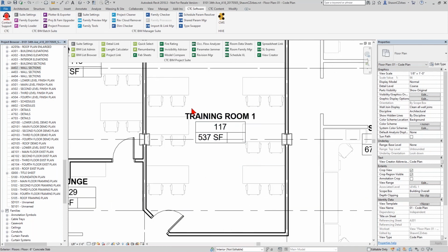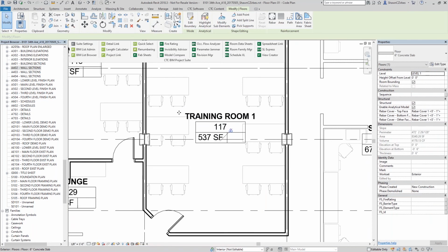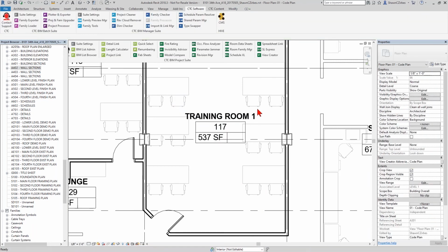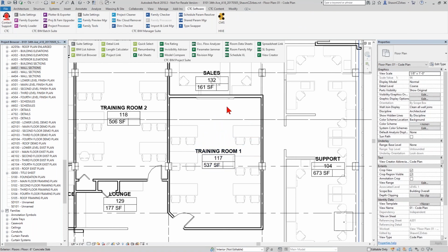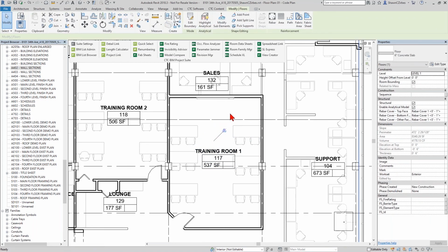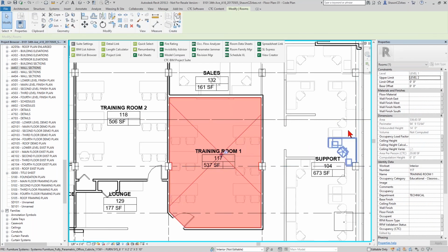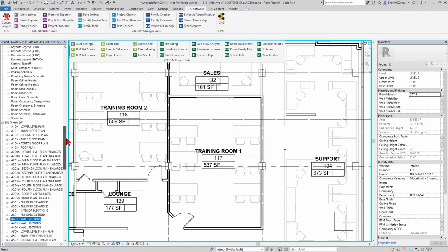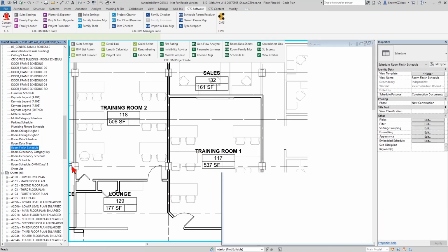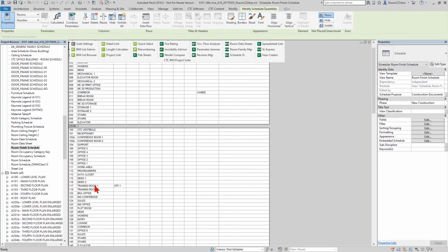Okay, you all probably know this already, but when you take an element in Revit, I'm trying to grab the room here. Come on, room, highlight for me. What is your deal? Room. Okay, let's hide this under link here to get rid of it. And there we go. There's my room. Okay, so I've got my room selected. And if you go to floor material here and you put in a value like CPT-1, you would probably not be surprised if I jump over to the room finish schedule and that floor material was CPT-1, right? So if I scroll up here, room finish schedule, magical. Right there, room 117, CPT-1. Like when I first started using Revit, this was amazing, right?